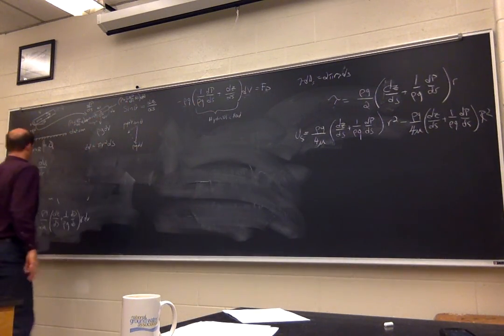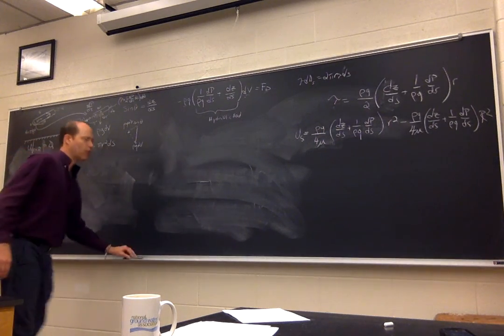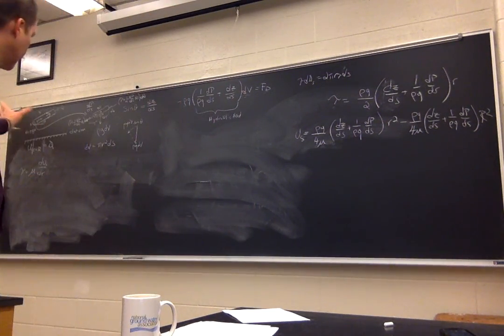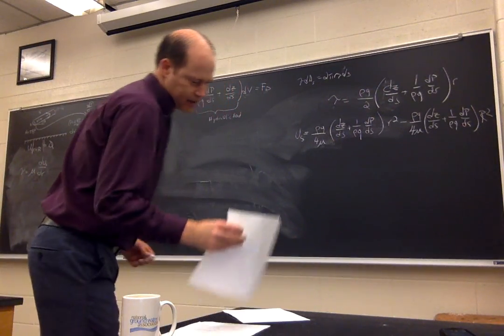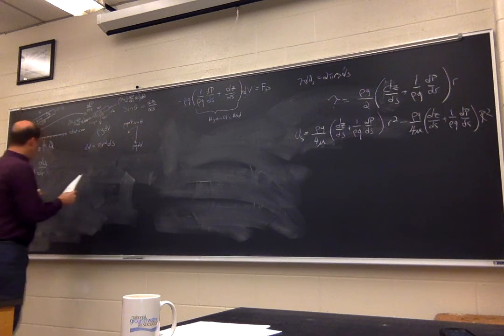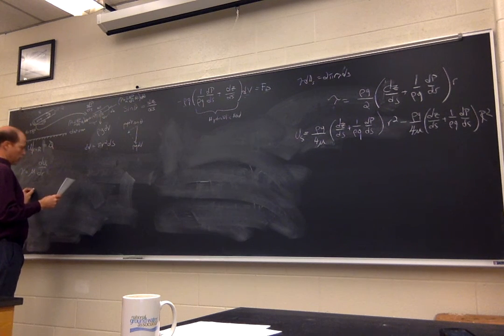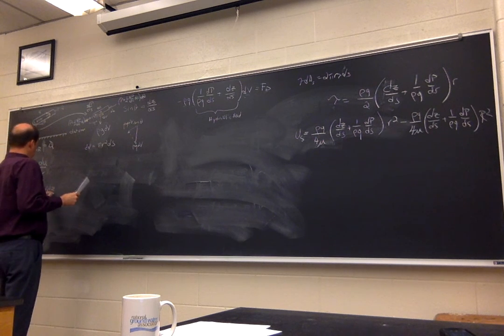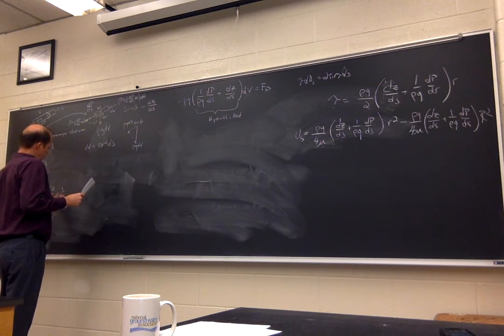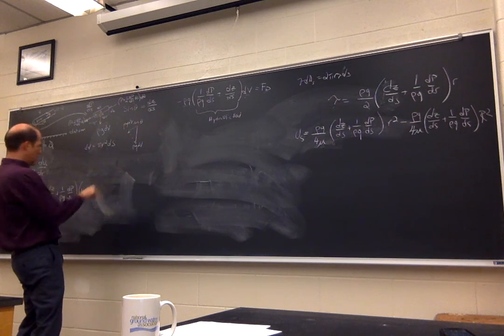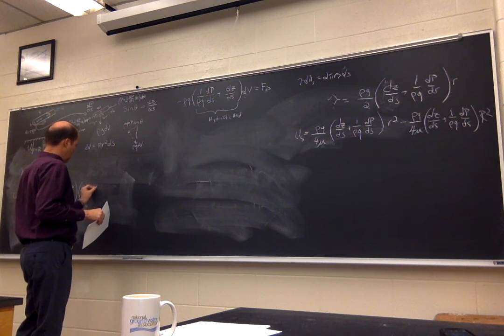And I'm going to go all the way back to here, and I'm going to write what my final velocity profile is on that side, simplified down to the velocity profile in the s direction is equal to minus rho g over 4 mu times dz ds plus 1 over rho g dp ds, times, because I switched the negative sign here, big R squared minus little r squared.